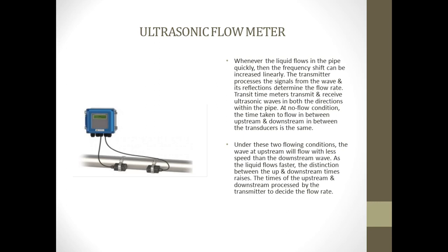Since the flow rate is related to the flow velocity, the effect may be used in several ways as the operating principle of an ultrasonic flow meter. The term ultrasonic refers to the fact that in practice the pressure disturbances are usually short bursts of sine waves whose frequency is above the audible range of human beings, say 20 kilohertz.